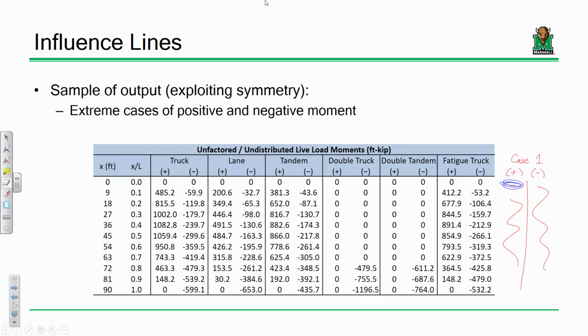So take those values, multiply them by 0.4, and what you're doing is converting just moments and shears on just some random old beam to how much of those moments and shears we can expect on this beam or that beam or that beam. You see what I mean? I'm not trying to give you the same answer that I just gave you, but what I am saying is all those transverse dimensions, slab thickness, girder spacing, all that, they are taken into account when you compute distribution factors. Does that answer your question?